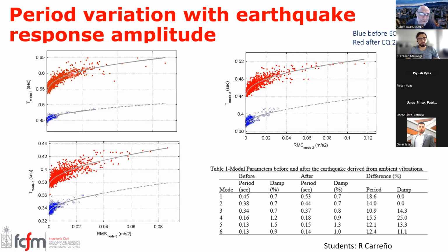So we know that this structure after damage, when it has displacement, reference displacements, these are not drift. It's a reference type of displacement. It's in acceleration units. We can discuss that later. But it tells me that it changes quite strongly as a nonlinear elastic response, and we have to consider that in order to develop a structural health monitoring system. That is a system that will tell the owner if the structure was damaged and hopefully where it was damaged.